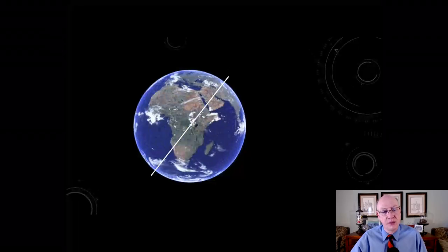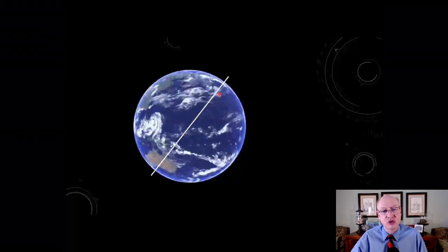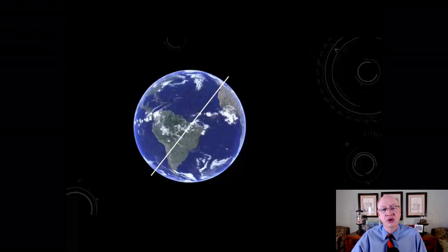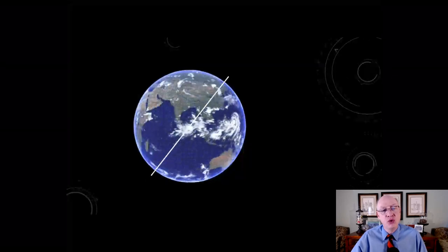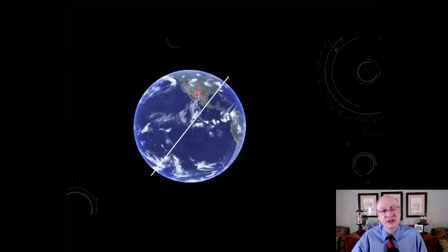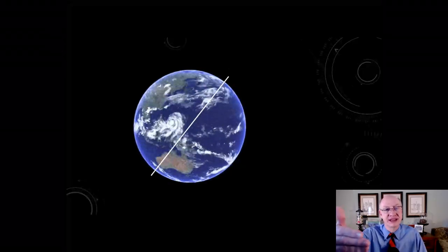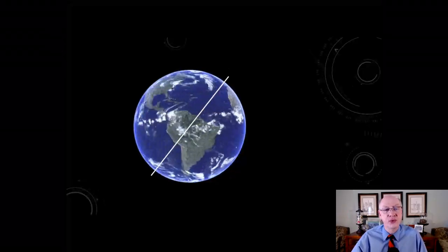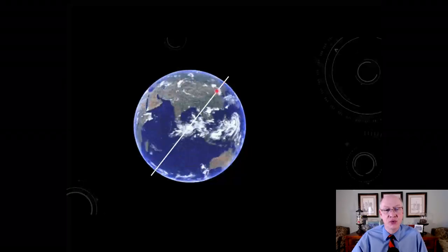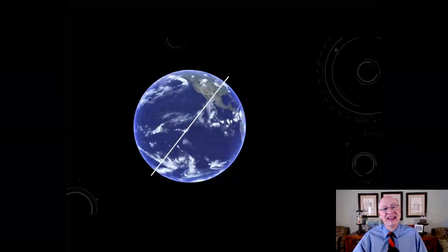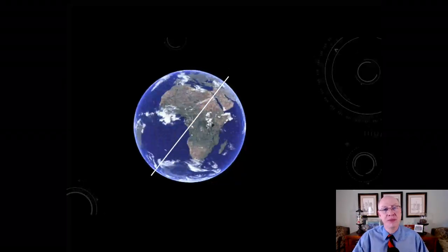So think about this orbit right here. This is the orbit of the International Space Station. It's tilted by about 51 degrees with respect to the equator. If you watch Florida on the Earth here, you will see that there are 2 periods of the day, one here, and then one when Florida is on the opposite side over there, when Florida happens to sit exactly below this orbital plane. That is your launch window. That is the moment you want to launch.